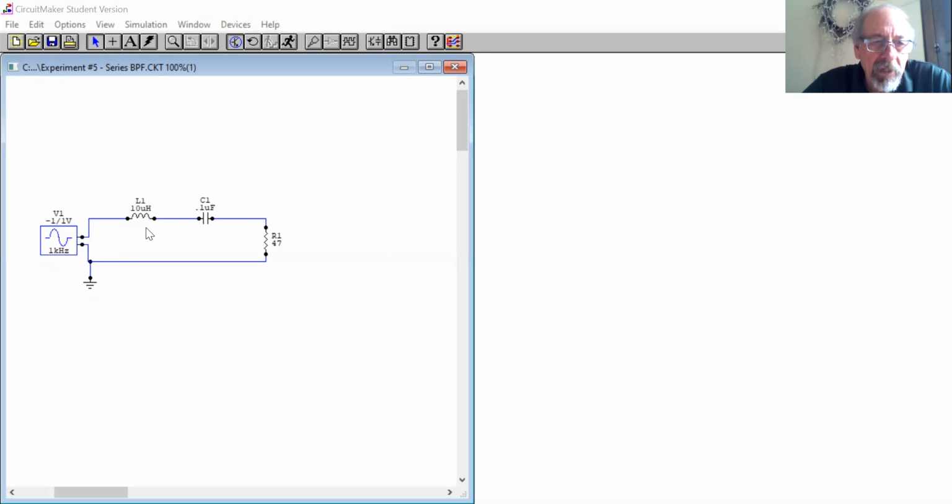Remember, I like to talk about Eli the Iceman. That's ELI, voltage leads the current in an inductor, and the Iceman, ICE, current leads the voltage in a capacitor. So Eli, the voltage can change instantaneously, but the current cannot. The current changes as the magnetic field gets energized. And the capacitor, the current can change instantaneously, but the voltage cannot. The voltage will build up in a charging curve, time constant type fashion.